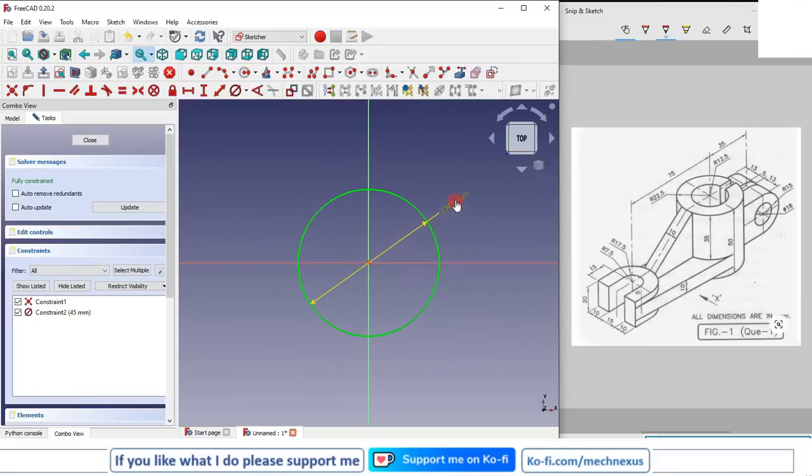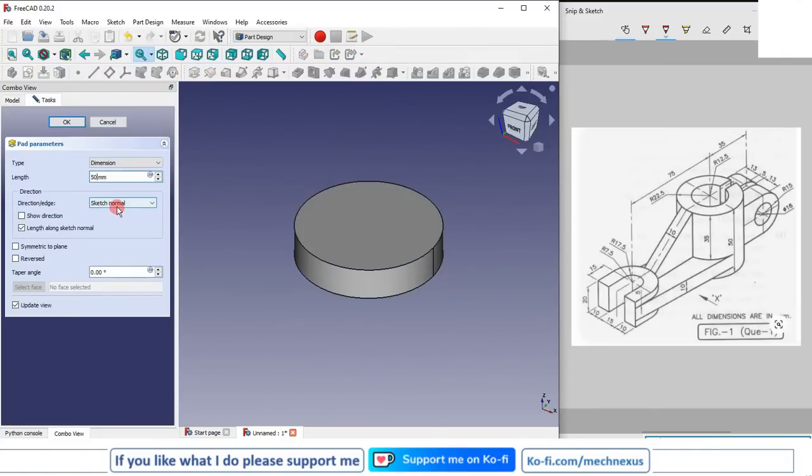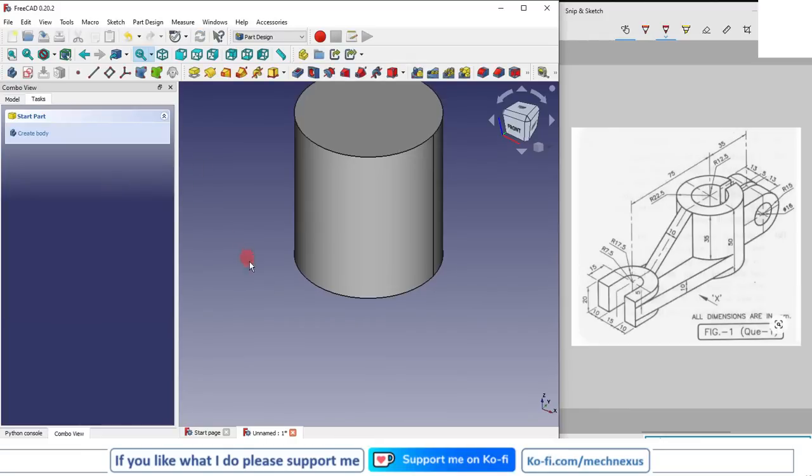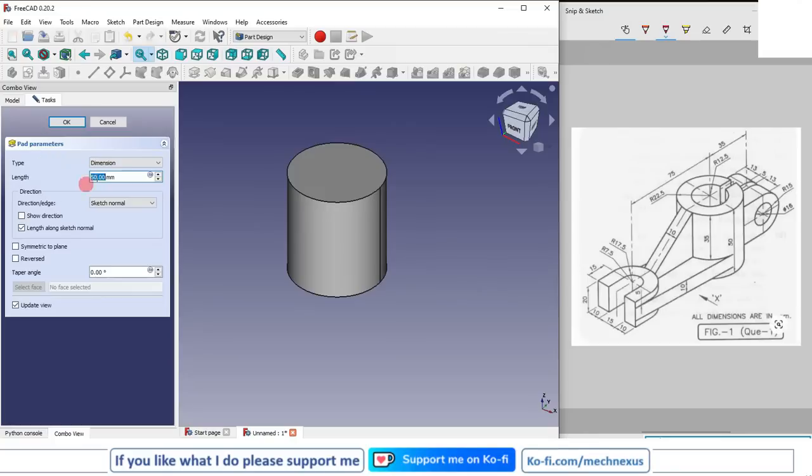So here I will close it and I will give the extrusion length of 50. So I will select on the pad and give the dimension 50. And now we will make this face. So for this we require a datum plane, or we can edit our extrusion into the 2 dimension.